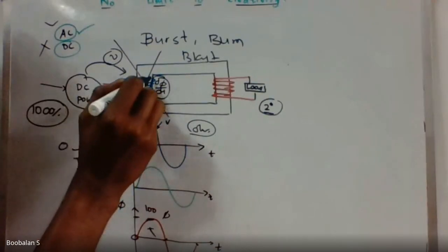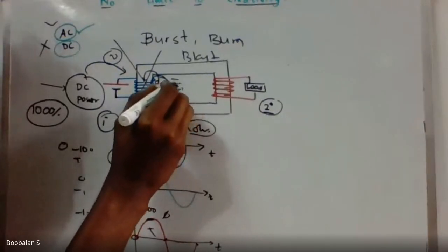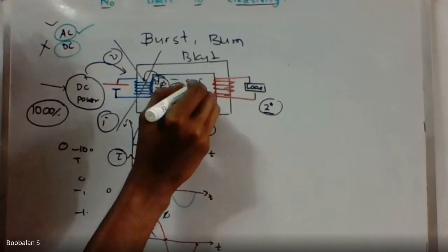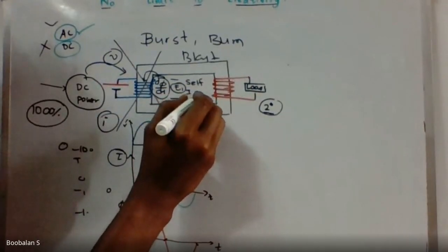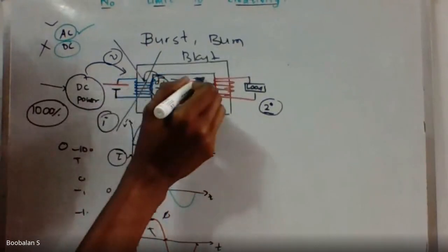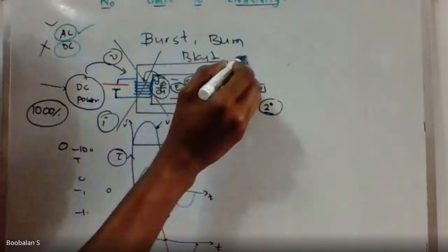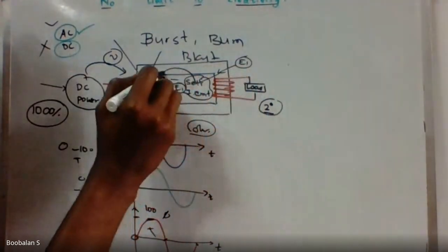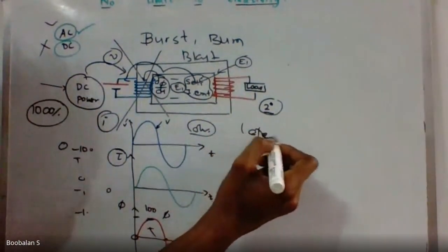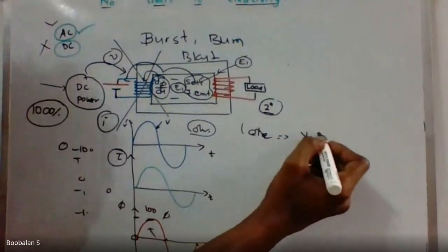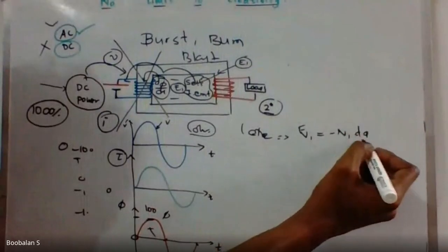So this is also a copper conductor. Definitely it will induce one more EMF across this coil. This is called my E1, that is called self-induced EMF. We have already discussed this. The self-induced EMF is now going to build up on this coil. This E1 induced voltage is now opposing my input voltage. This is what is called my Lenz law, right? So Lenz law indicates that however much voltage E1 builds up depends on the number of turns and how the flux line is changing.